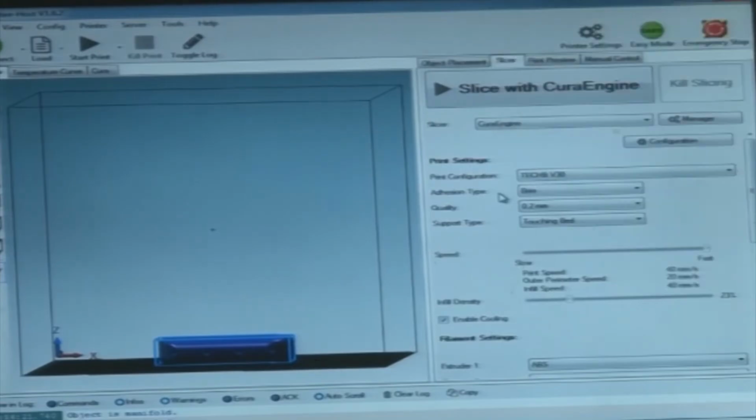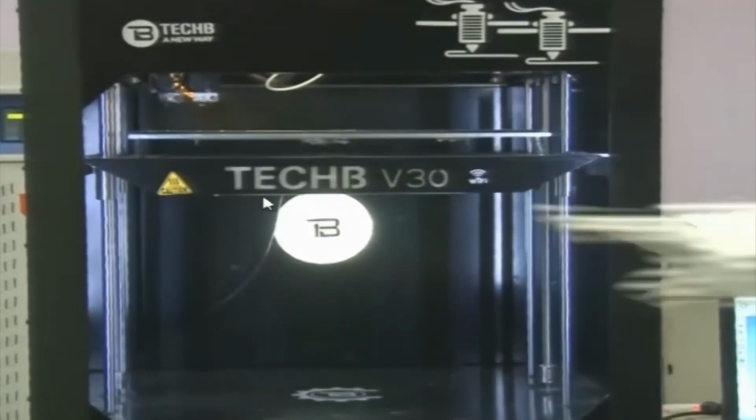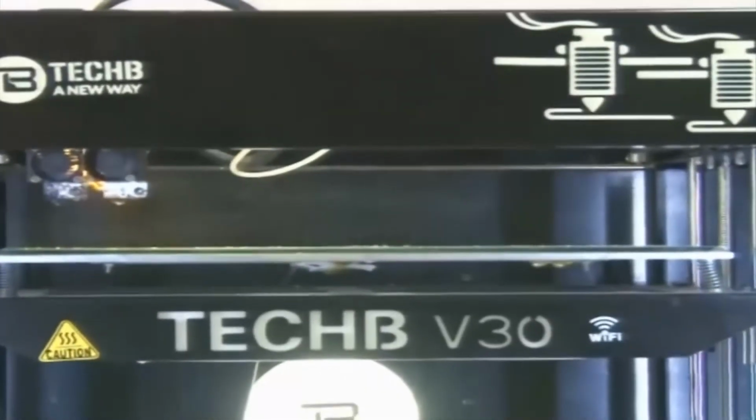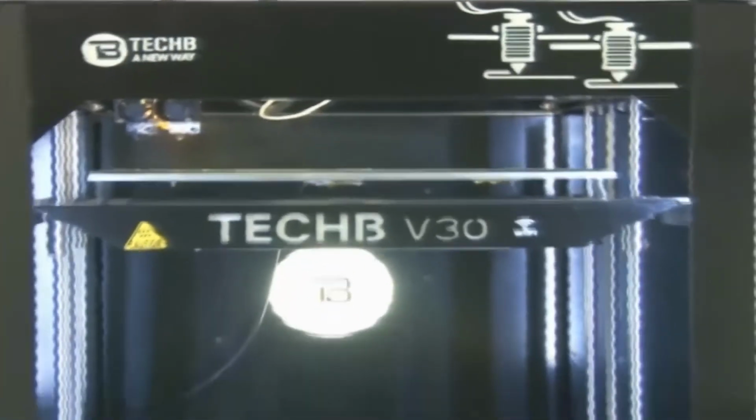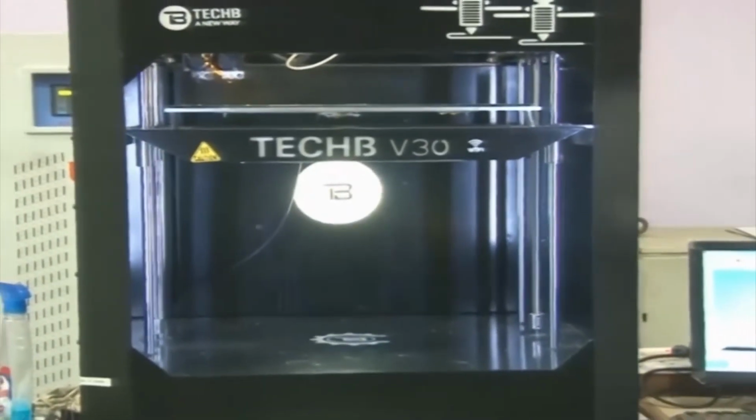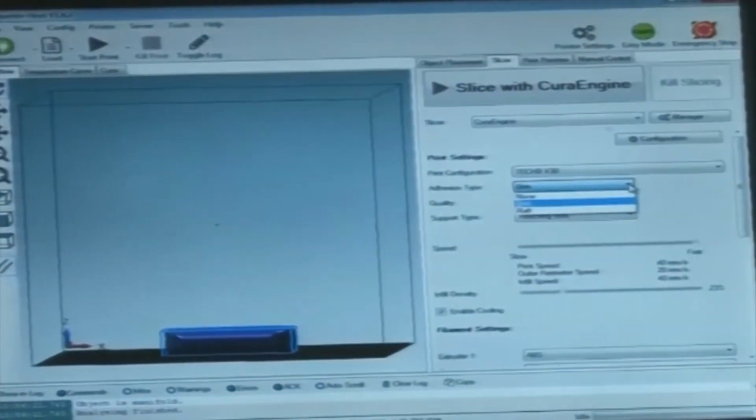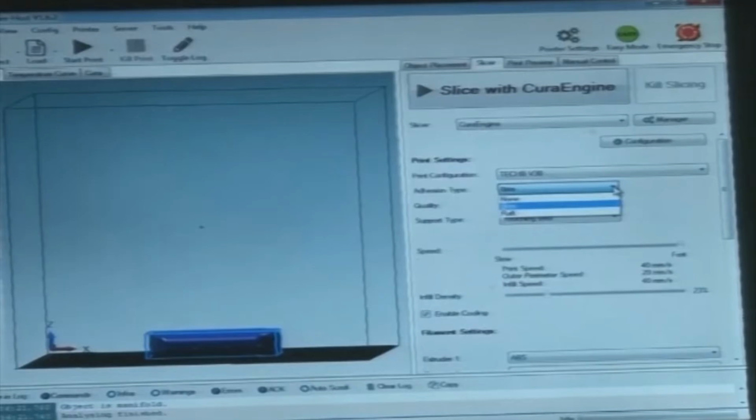This plays a very important role, because this layer will stick with the machine, this tabletop, this hot plate. If we do not provide any extra material to the periphery, the job may stick on the bed, and we may lose some features on the base of the job. So we use this feature only when we find that more material has to be added, when more area is necessary.